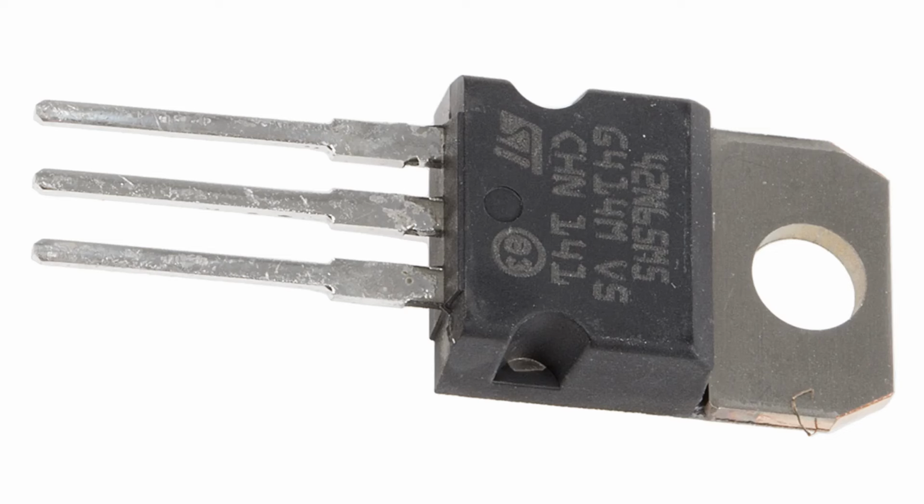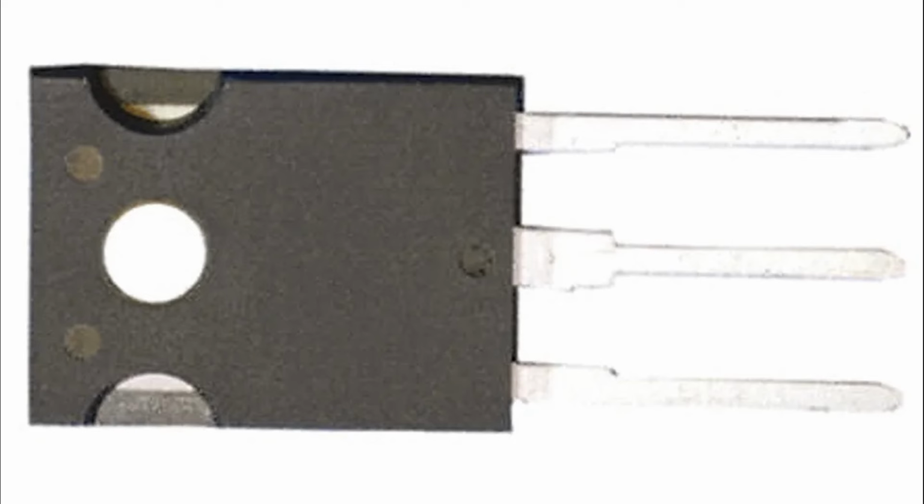On state, saturation/linear mode. Condition: when the gate voltage exceeds the threshold voltage, V_TH, the MOSFET turns on, allowing current to flow between the drain and source. Current flow: a conductive channel forms in the semiconductor material, allowing electrons, in an N-channel MOSFET, or holes, in a P-channel MOSFET, to move from the source to the drain. Characteristics: the MOSFET operates like a closed switch, and the resistance between the drain and source, R_DS(on), is low, enabling efficient current conduction.